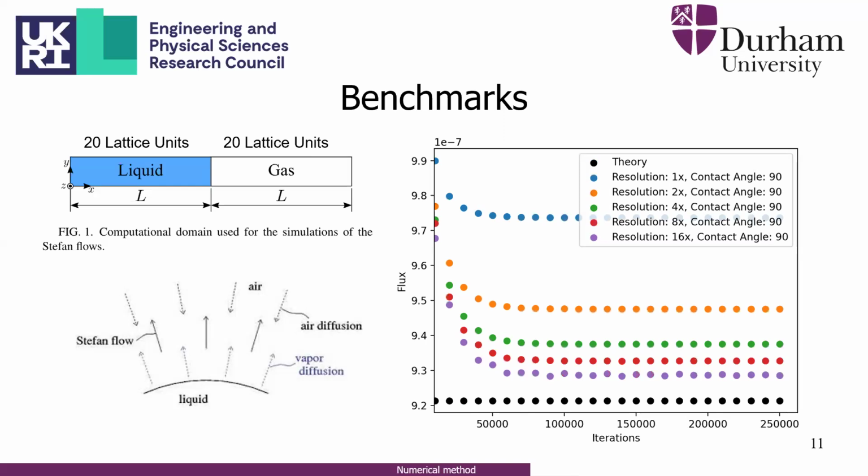The last question from my side. You said that you track the humidity also with the convection diffusion. How do you know what's the value for the humidity? For diffusive evaporation, we're assuming that on the interface it's completely saturated with vapor, because it's always instantly refilled, since we assume it evaporates really quickly compared to the rate that diffusion can happen.